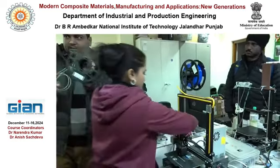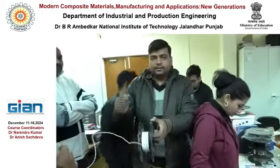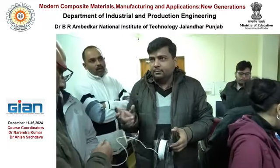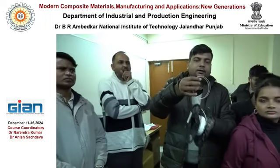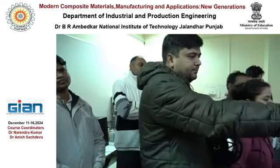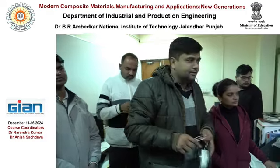So this spool, the material comes in this form, in filament form. And yesterday I talked about, if you are planning to make any composite material for the FDM process, what you need to do: you need to ensure the diameter. The diameter should be 1.75. Vivek, can you give me that vernier caliper? So let us check the diameter of this filament, right?